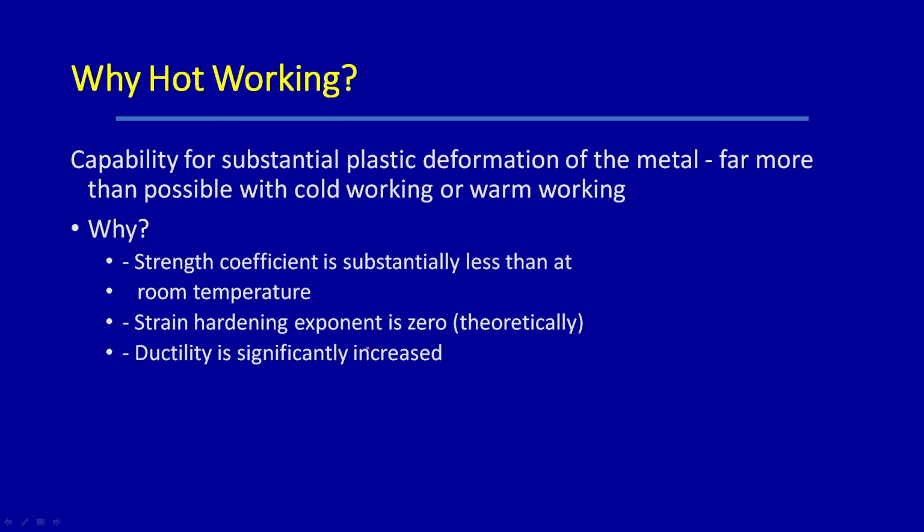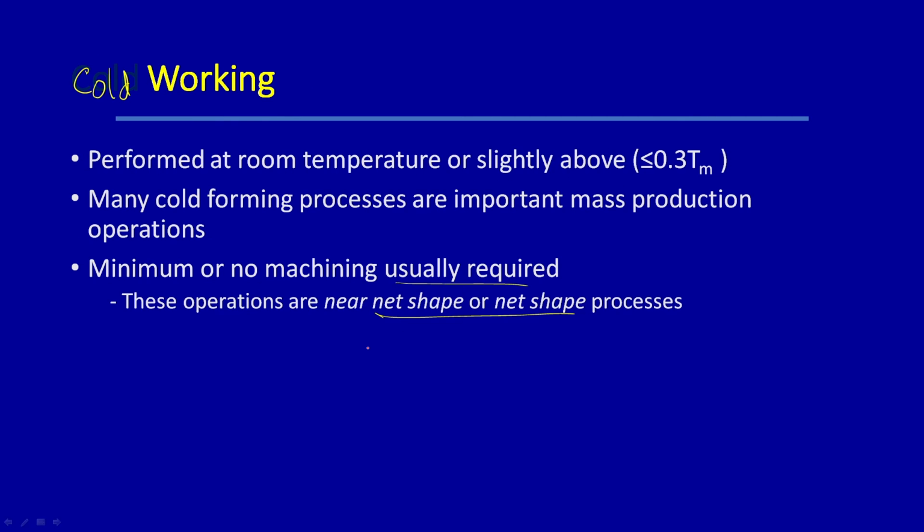Theoretically speaking, it can go to 0, but normally it does not go. And the strength coefficient K is substantially low here. So, as compared to room temperature, the material can be deformed very easily. But the problem is that at high temperature, if you want to deform at different strain rates, then the stress required increases, and I discussed this a lot and I will discuss it again.